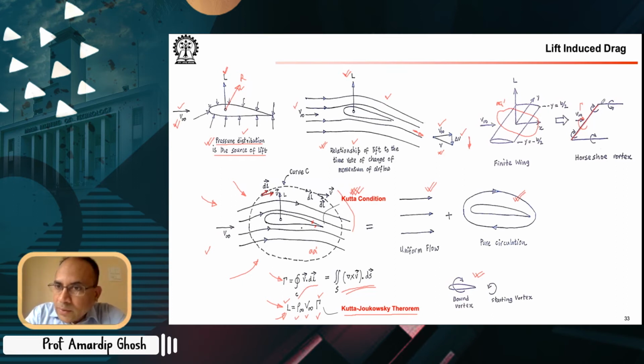On the other hand, if we see these lines and these lines, for the single horseshoe vortex approach, whatever strength of circulation we have here will actually be here because of that cross section. So the inflow of the vortex filament strength is equal to the outflow of the vortex filament strength. If you have inflow here, then the outflow here will be the same, and we will show what this inflow and outflow is. If you remember, it is essentially this thing that we have shown previously.